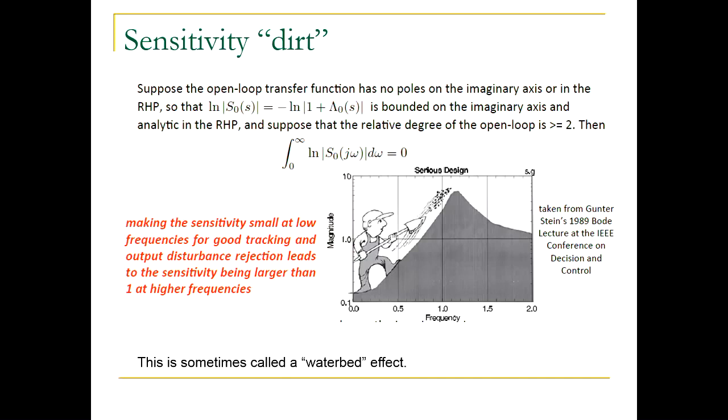So, are there any questions? By the way, this is called the waterbed effect. It's like a wave: it reduces on one side, it increases on another side. Any questions regarding this? Or you can just move the peak to a high frequency. Depends on the plant and your specific situation.